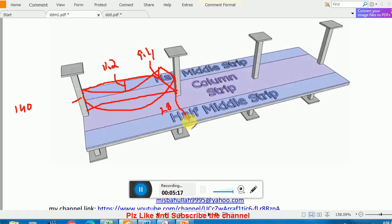Again, if we come toward this side, the picture will be clear. The moment is 0, then it is positive, then it goes up, and this one will be the value. So here you see this kind of shape. In 3D you see this kind of shape. So you now understand the moment diagram, how it looks. This one again is 9.4, and this is the positive moment, which is 11.2.